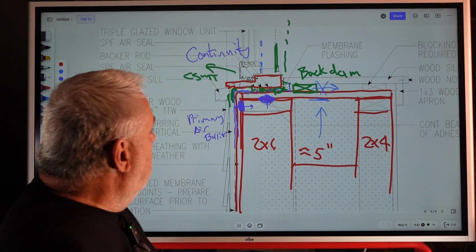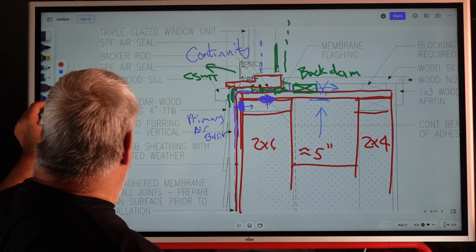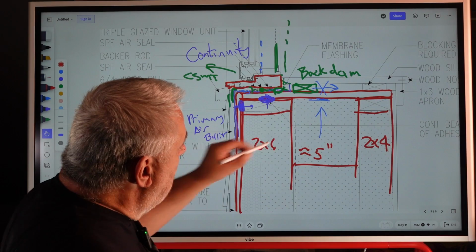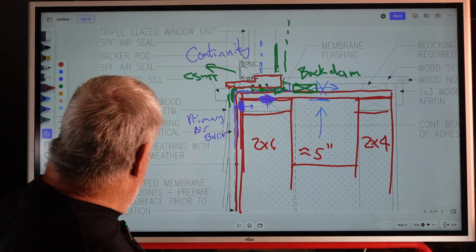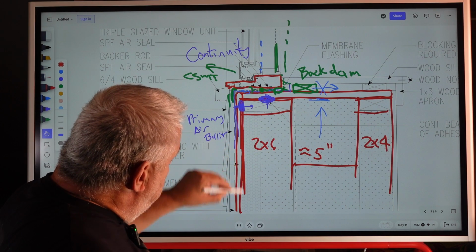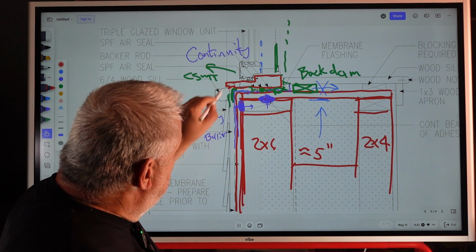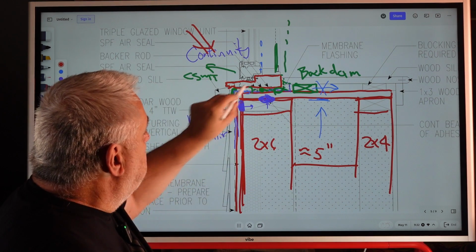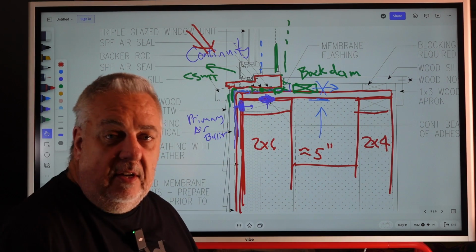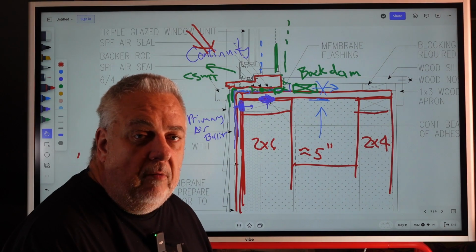The risk here, you know, a couple things. Pushing that window all the way out to this outside edge here, that's really good because I minimize any water intrusion in this area, right? Because I don't have much of a sill there that puts me at risk.